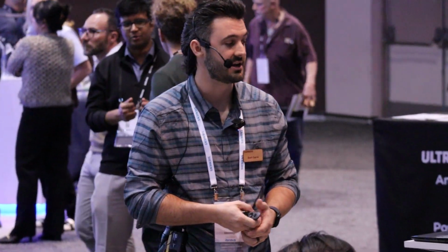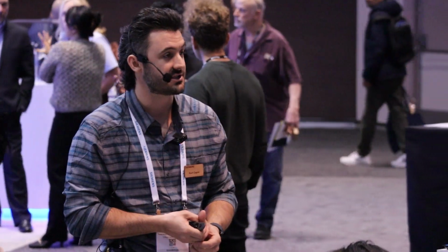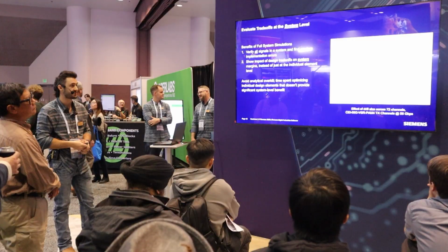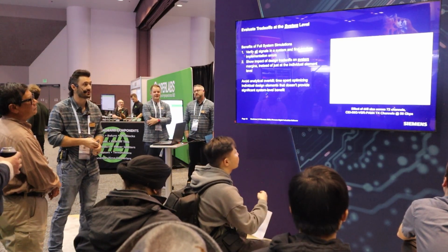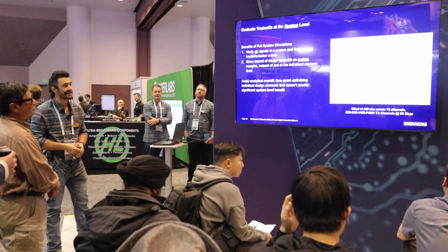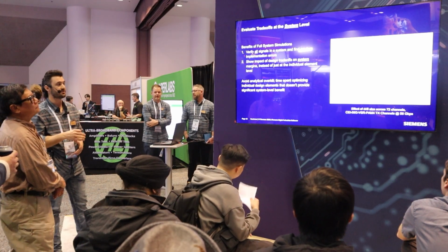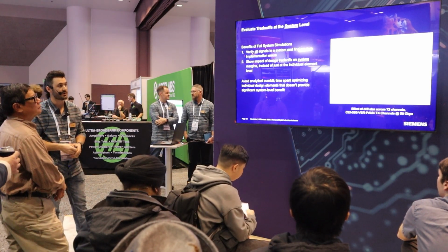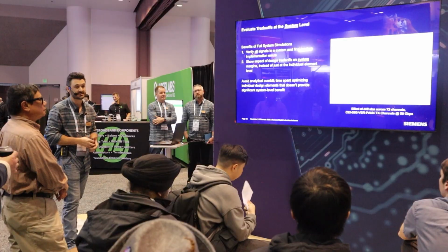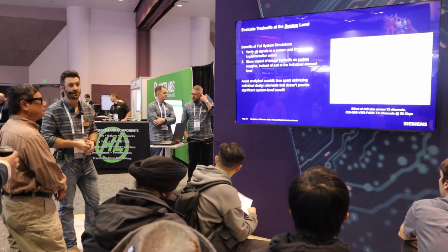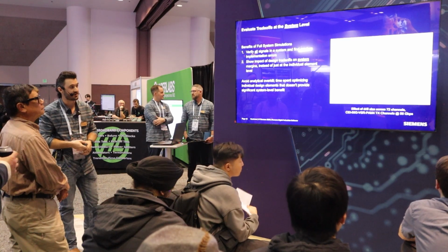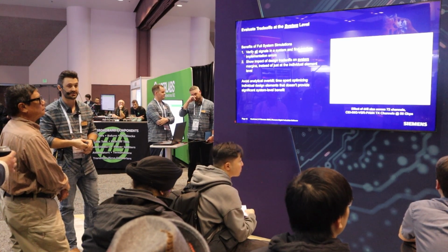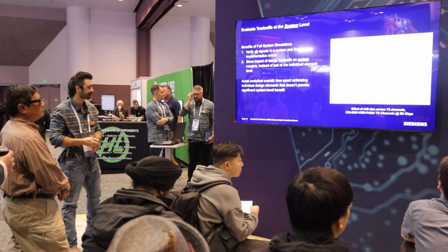In this plot on the right here, we're looking at the effect of drill performance on those 56G VSR channels. The blue dots show the set of signals simulated with a 12.3 mil via drill diameter. And then the set of green dots show those same signals simulated with a smaller 9.8 mil drill diameter. So at a quick glance, we're able to see the effect of the drill diameter change on the system level performance of all of these nets. And that plot is showing eye height versus eye width on the X and Y axis for those channels compared with the protocol requirement.